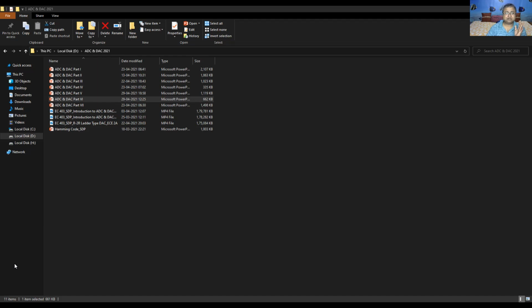So the T flip-flop is a negative edge triggered flip-flop here, and it is triggered according to the negative edge of the MSB, that is called Bn-1. If it is an n-bit up counter, then it will count from 0 to 2 to the power of n minus 1.